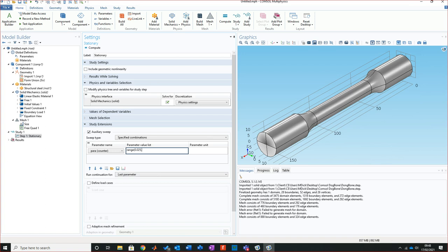Now, if I want to move in multiples of that, all I'm going to do is say 0.025. So then it says, at the next iteration point state, I'm going to move 0.025 and just add them up. As it goes through, what it does is it applies that to the force, multiplies that into the force, and then we get a gradual build on the force.